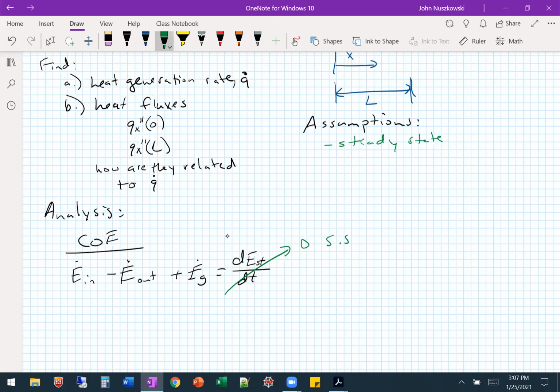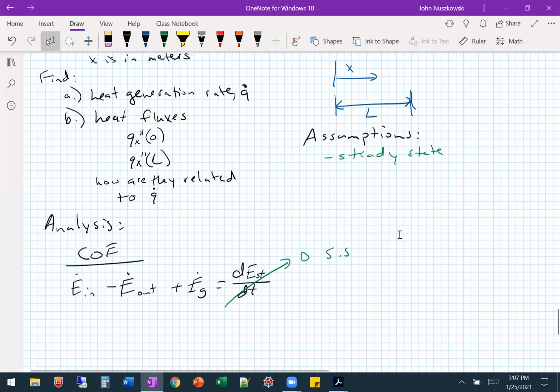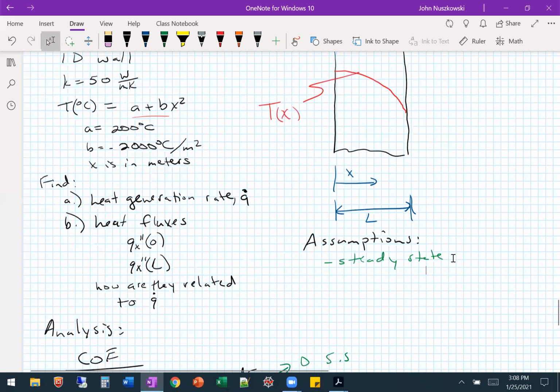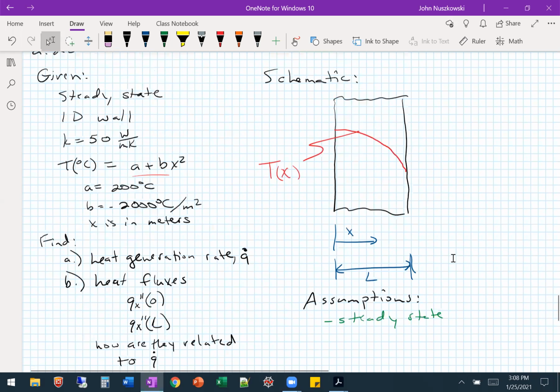We have flux in and flux out essentially with the temperature distribution. So we can say heat flux times the area using dT over dx. Yep. Because it's in 1D, we could also use the second method. We'll do that next, we'll wait a second on that.